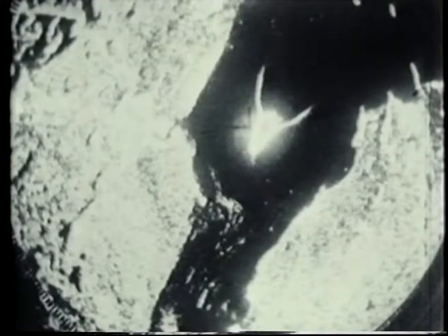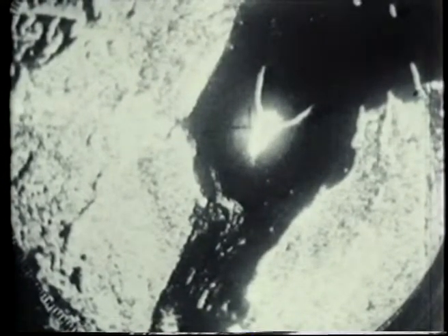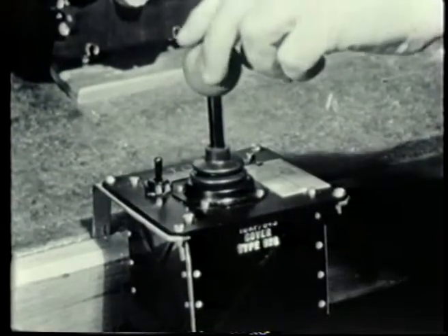Here is a still photograph of a PPI display. Information may be abstracted from the display with a high degree of accuracy by the use of electronic markers. These consist of a range ring and a bearing line. Their intersection forms a datum which may be placed on any selected radar response by this joystick.